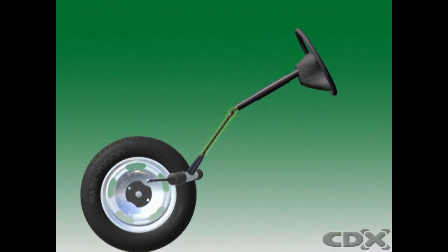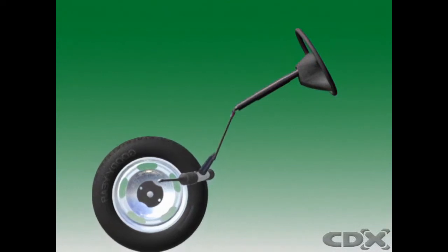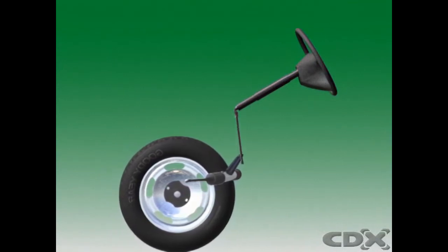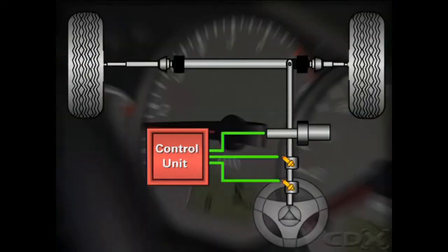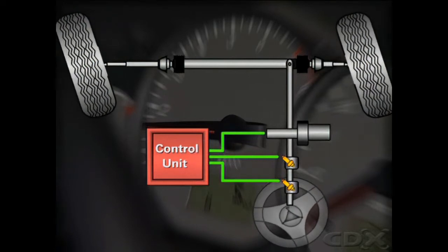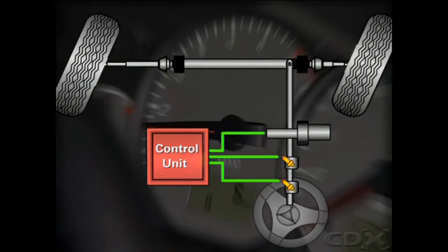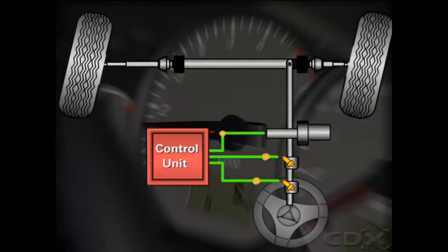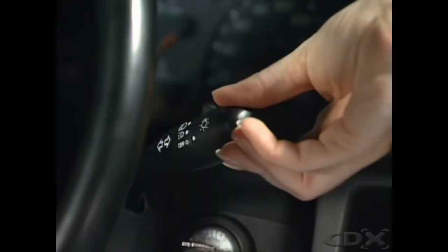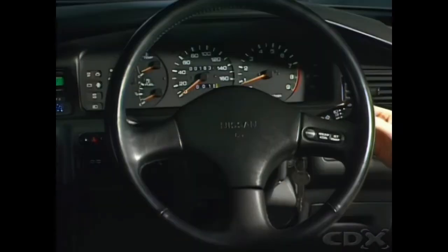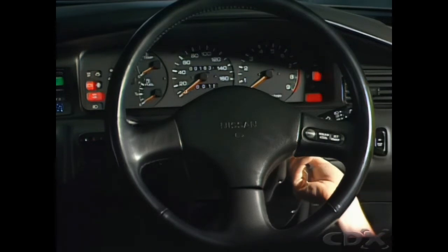Some steering columns have an intermediate shaft, which runs at an oblique angle from the column to the steering gear. In a collision, the universal joints on the shaft allow it to fold under, preventing the force from impact being transferred directly to the column. Some manufacturers fit sensors and control units to the steering column, which provide information to steering control modules as part of an electric-assisted or four-wheel steering system. The sensor and control units are able to sense rotational pressure exerted by the driver and control both the speed and direction of the electric motor. This motor is contained inside the steering rack and provides the steering assistance. The steering column may also include switches for lights, indicators, wipers, and an ignition switch and lock assembly.